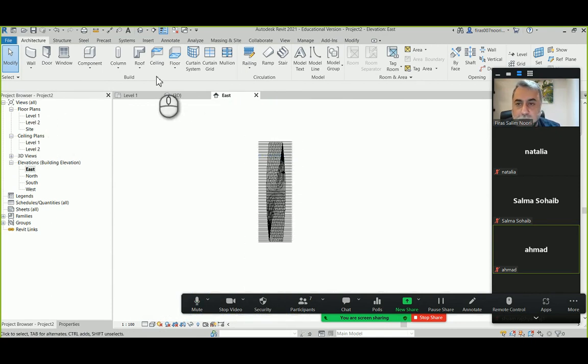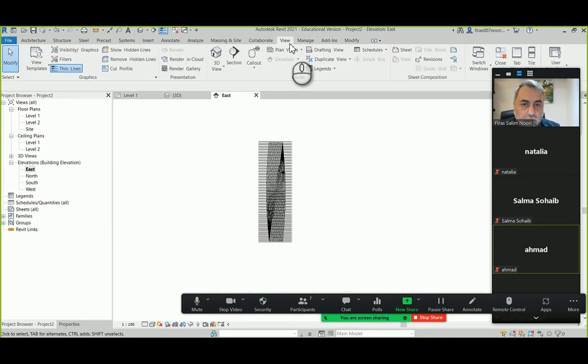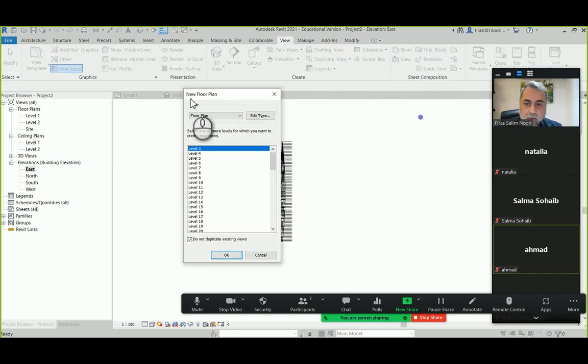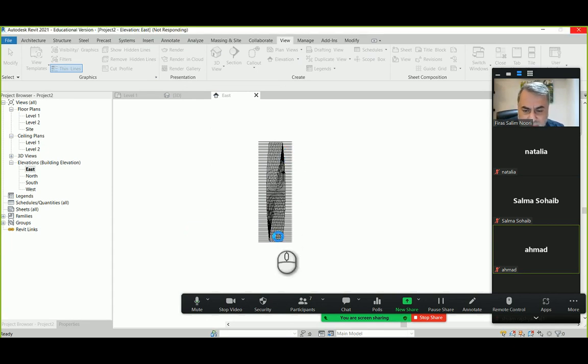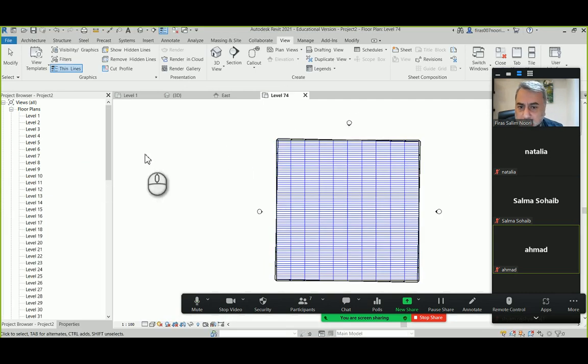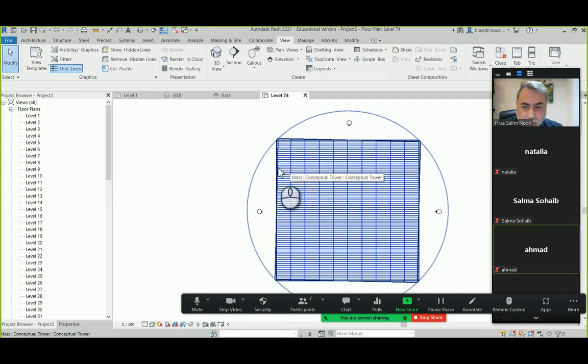Now how you do that is super easy. Go to view. روح إلى الفيو. عندك ليفلات بس ما عندك طوابق ولا بلاناتها, not even plans. Go to view, my friend, plan view, my friend, floor plan, and بضغطة رجل واحد, just make sure that this is selected, hit shift and the last one, and then hit OK. Now Revit will generate for you an automatic plan for the 73 plans.